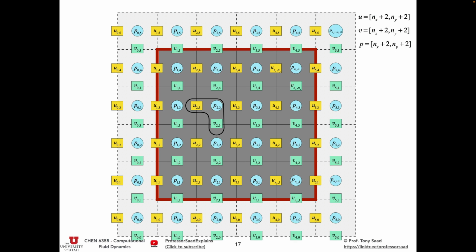This is the discretization piece of it. We have all the components for it. The time integration scheme is simple forward Euler, n plus 1 minus n over delta t, so that term is easily added to the equations. We have all of the ingredients necessary, but we're still missing a solution algorithm. Remember last time I spoke about the difference between the numerical method and an algorithm. The purpose of the algorithm here is to figure out how we can get a pressure where there's no equation for the pressure, which is the projection algorithm that we discussed last time.